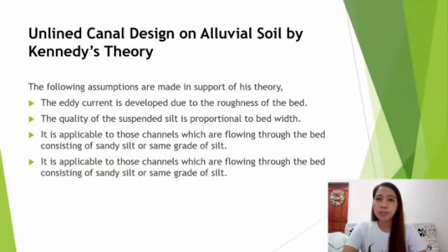Okay, so now let's proceed to our second method. The second method is for unlined canal design on alluvial soil by Kennedy's theory. After a long investigation, R.G. Kennedy arrived at a theory which states that the silt carried by flowing water in a channel is kept in suspension by the vertical component of eddy current, which is formed over the entire bed width of the channel, and the suspended silt rises up gently towards the surface.